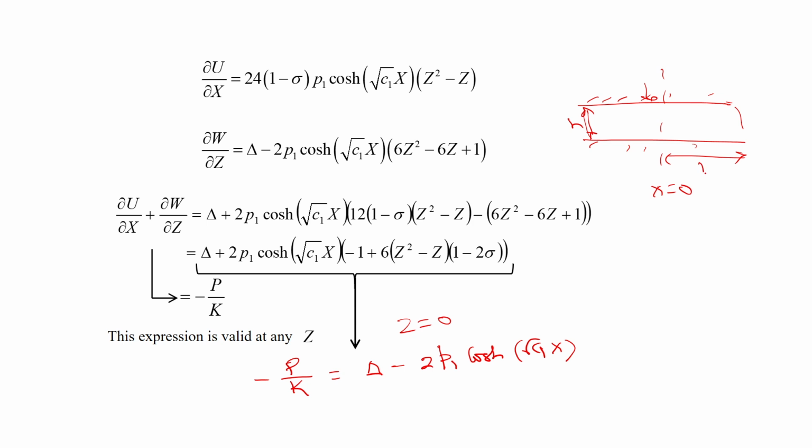Now what happens is that at x is equal to L by 2, this pressure becomes atmospheric. So, it is 0. Whatever pressure capital P is there in the film will be equal to 0 at plus or minus L by 2, okay. So, at this end and this end, pressure is 0 because it is exposed to the atmosphere.